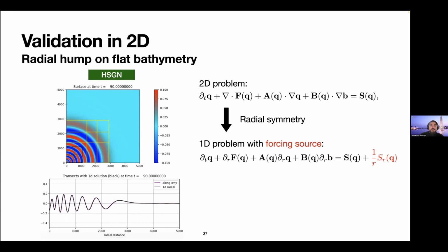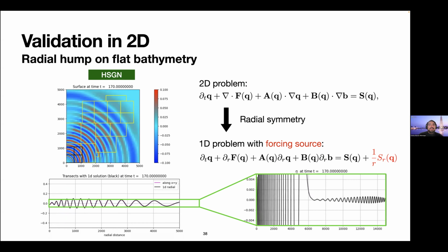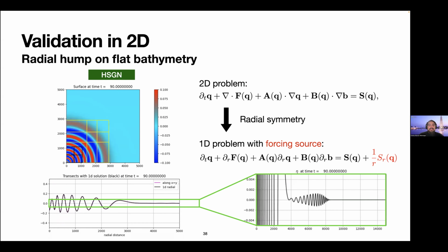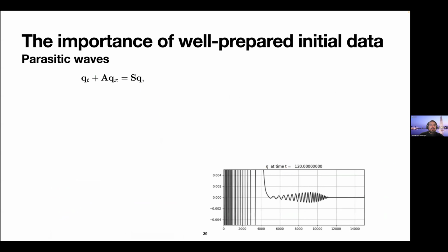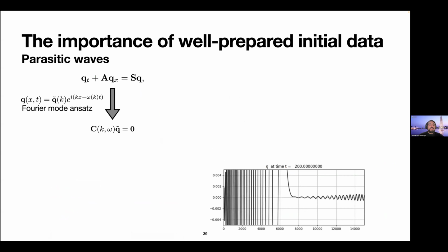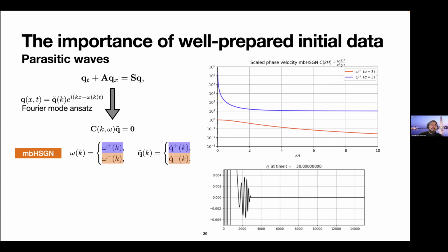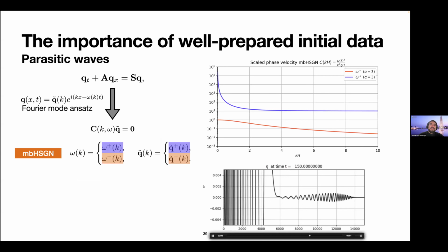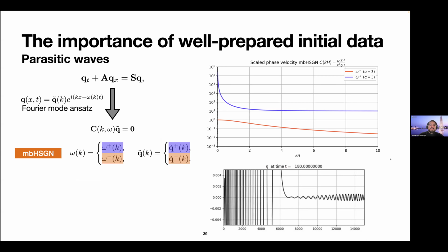There is some very fast, small amplitude wave train that is traveling faster than the physical wave train. And we can explain this artificial wave train again through the dispersion relation. These hyperbolic models have more equations than the original equations, so the original sets of equations have artificial phase velocities. So here in orange, you have the phase velocity that will converge to Euler in the relaxation limit.